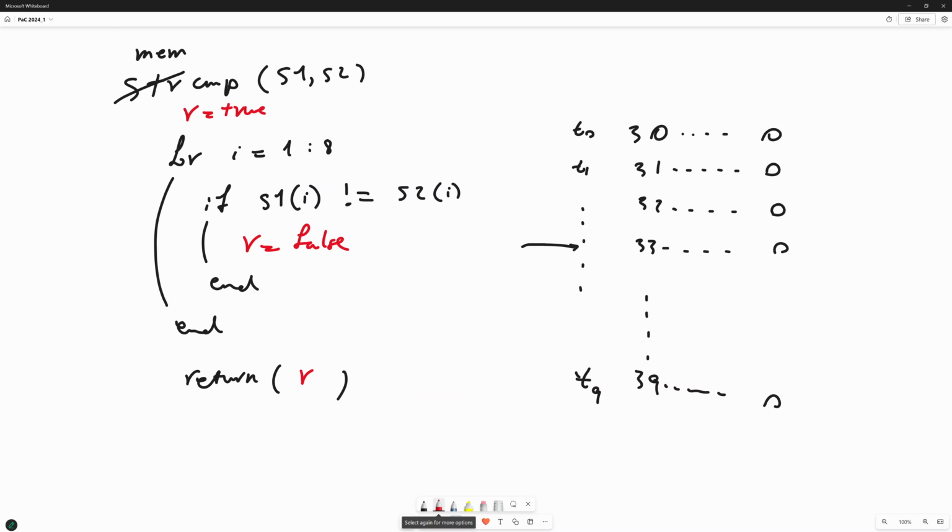Then this is pseudocode, or let's say high-level C code that you write. What happens in assembly? Because you have to look at the machine code. Every instruction in the machine code takes a different number of clock cycles. Then you may say, I don't do it because it goes through this operation and the other one doesn't. So what I do here is say else, no operation, NOP. If it's not correct, it does something; if it's correct, it goes to the NOP, and then the number of instructions is the same.